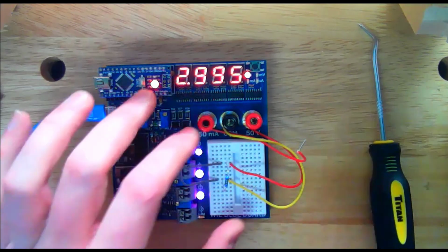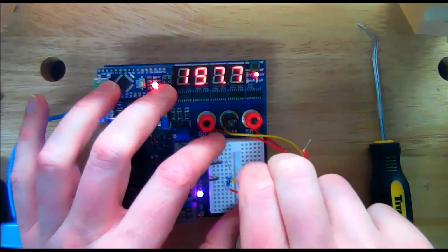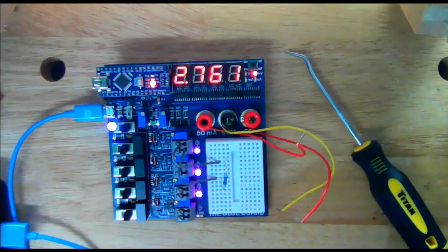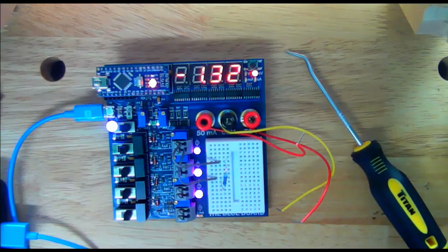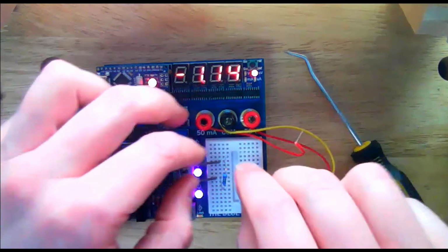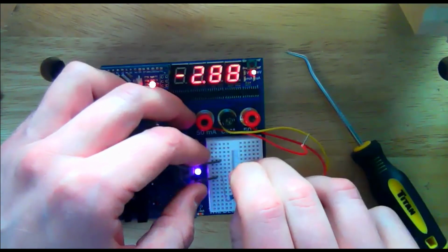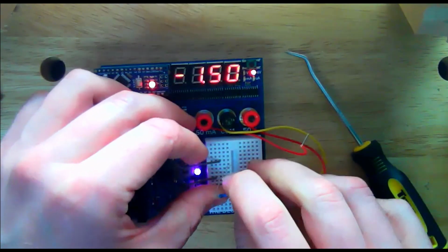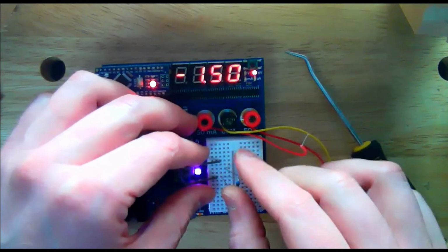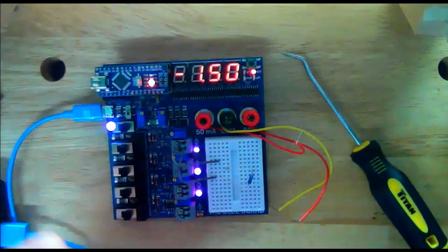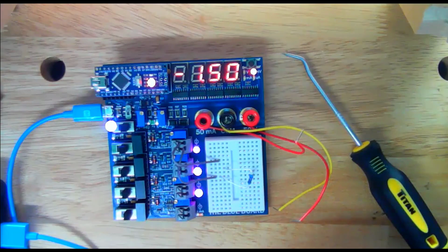Let's say we want to measure a current. So right now we have 3 volts flowing through our resistor. Our resistor is still connected. Whenever you want to measure current, you have to break the circuit. So it's a little hard to see right now, but what I will do is I will move one side of this resistor to a different row. Maybe if I bend the resistor over, you can see. I moved one side of the resistor to a different row.